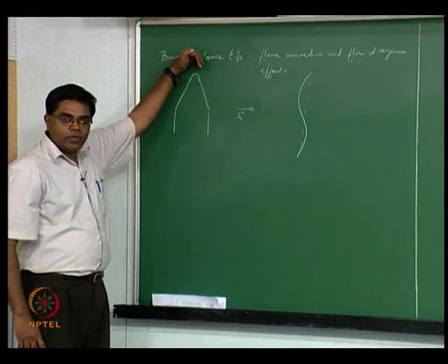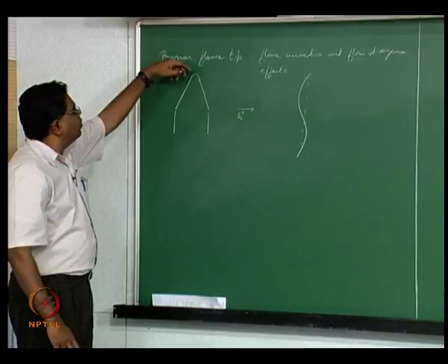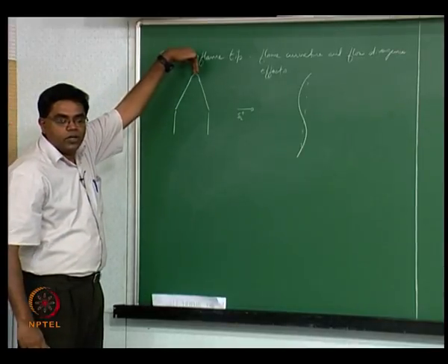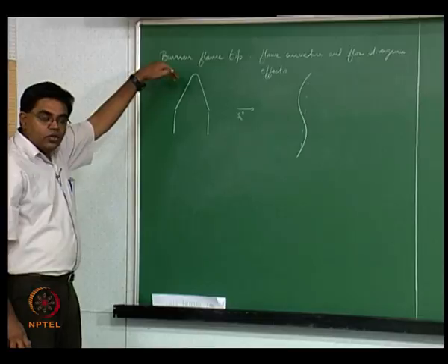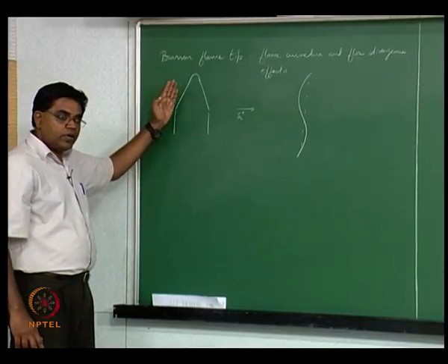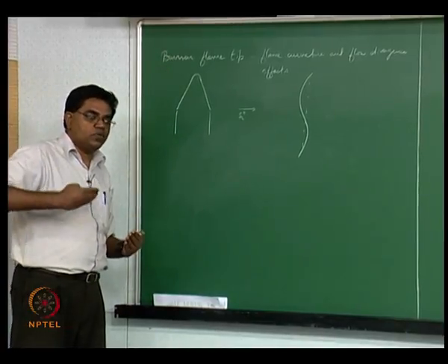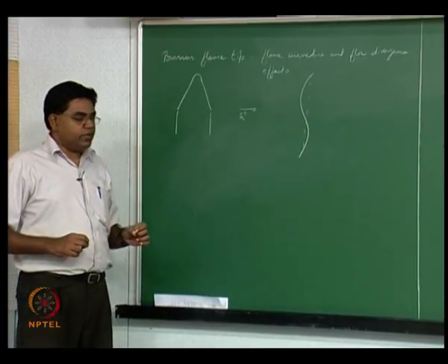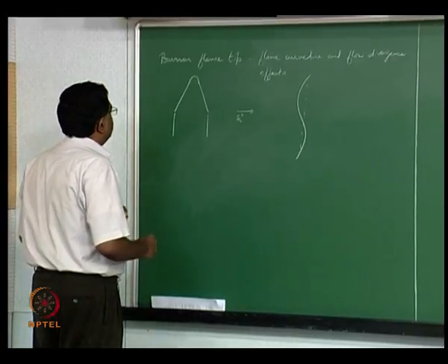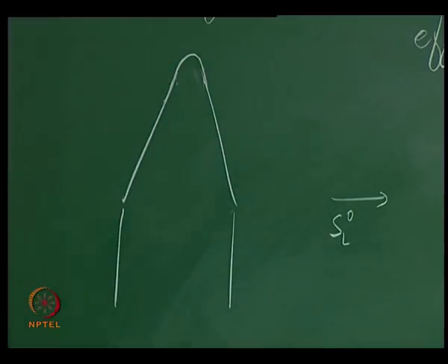But that's true for most of the shoulder of the flame. If you now think about what happens to the tip, no matter what the flame speed and flow velocity balance is, the tip also always has to propagate against the flow directly, right? Which means no matter what the flow speed is and how the flame speed is able to balance that, the tip always has to adjust itself to match the flow speed to the extent it can. So the question is, how does that happen? What we find is we now have to think about a locally highly curved flame there, and see what happens when you have a flame that is so curved.